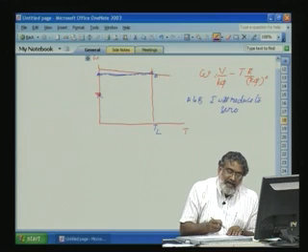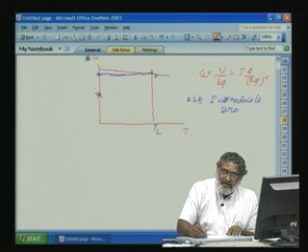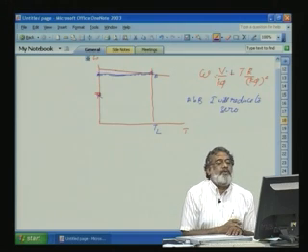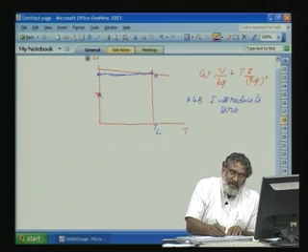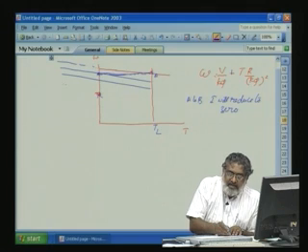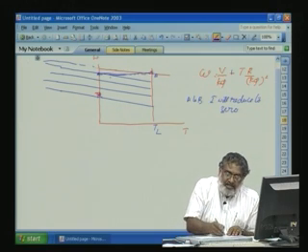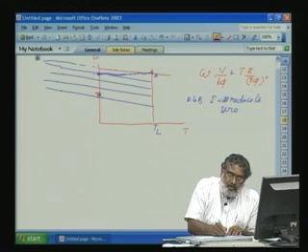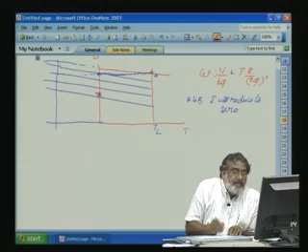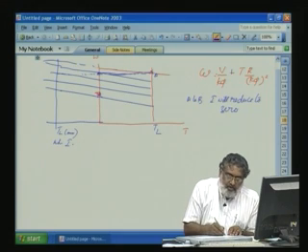Okay. Then as the current increases, now the torque is negative. So, this equation instead of negative, it will become positive. Okay. So, all these parallel curves we can extend to this side. So, this is during the regeneration period. Now, but the speed cannot change. So, system will go through various parallel curves and come to the maximum negative torque, depending on the machine rating. That is the TL maximum, where I is equal to maximum negative.